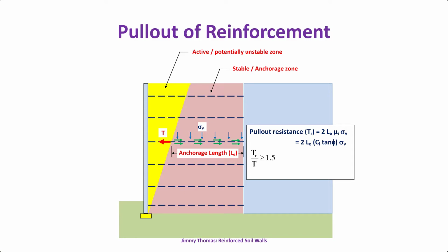And again, see, suppose it is a geogrid, then if you do actual design, normally the pullout problem happens only here. Like if you look at the lower layers, the anchorage length is very large, plus the normal stress is also very high. So typically if you look at an actual design, the factor of safety may be 30, 40 of that order, like that.